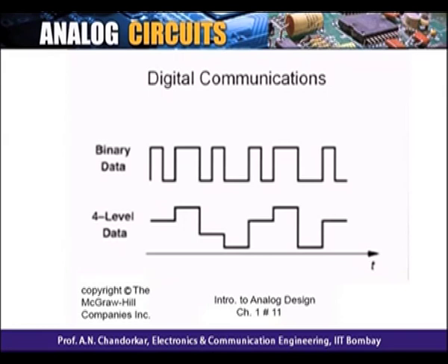This is what I say is going to happen, that people may look for multi-level digital data, because the analog part can then be broken into more levels instead of 2 only. So the newer research is converting this so-called analog looking signal into 4 level, or even multi-level, digital; right now 4 is what is being attempted. So why analog? Probably I am trying to answer why analog.